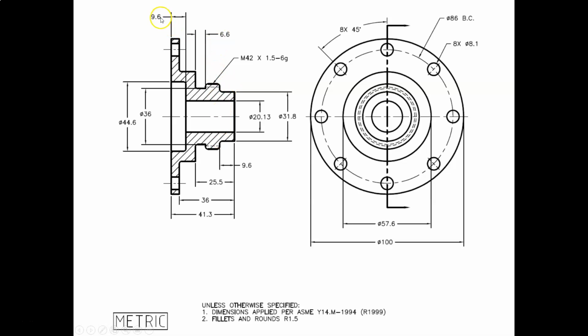And then the other dimensions are just the positioning or location of each one of the cylinders, so that we know where they lie. Okay, so again, if we look at the drawing, if we look at the part and we break it down into its shape and size description, you can start to understand what your job is going to be.